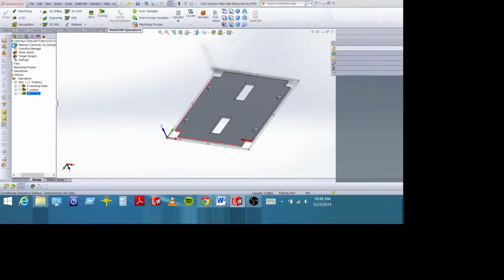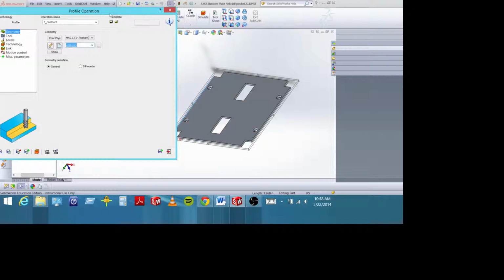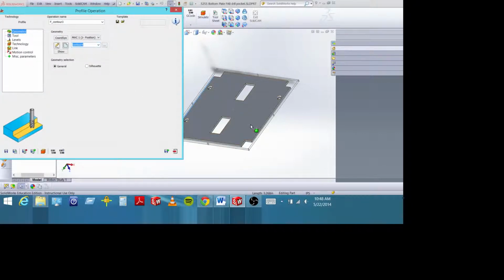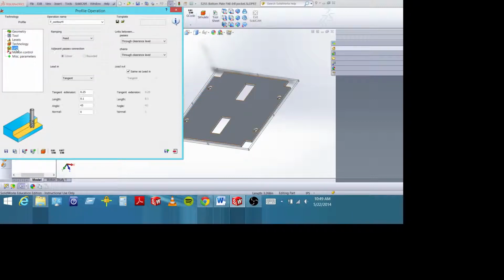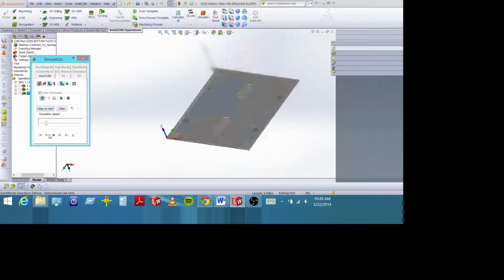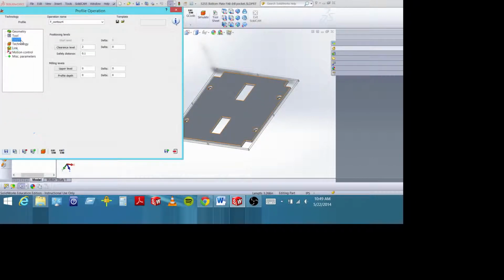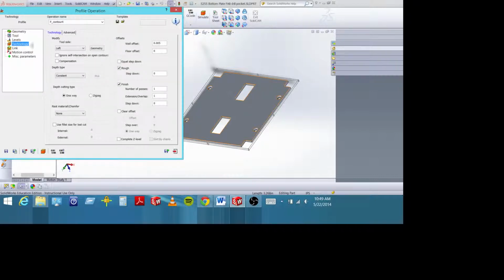and accept this geometry. Now, this is where we really want the lead in, lead out. I don't want to start right on this point, so I really want that lead in, lead out. I have it, so that's good. So let's resave and calculate and re-verify. That's what it's going to do there. See how it's leading in, leading out? Now, I should probably kill that overlap. That's a little overkill there. So go back in here and change my overlap.